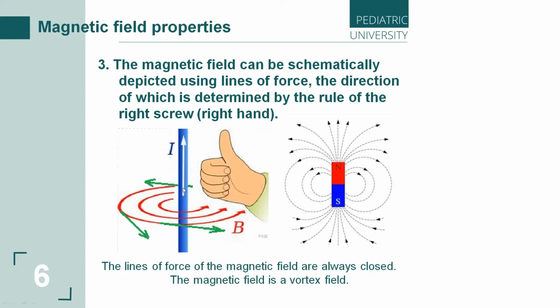Let's take this conductor as a pen, yeah? We can show it using our hand, for example, taking the pen in the right hand as if we wrap the conductor. And what happens? These 4 fingers will show the direction of the magnetic field lines. Let's see it again. Our 4 fingers can show us the direction of the magnetic force lines, as in the picture.